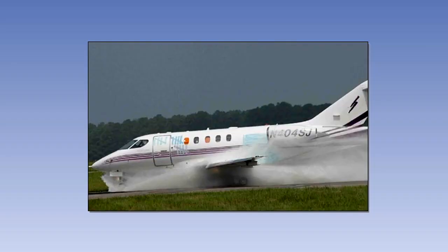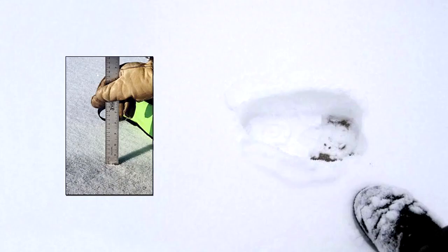There are other effects which runway contaminants can have on aeroplane performance, which include the possibility of a power unit failure due to water ingestion, directional control problems, and possible structural damage. It is therefore vital that the pilot be aware of the type of runway contamination, its depth, its extent, its effect on the braking, and of course its overall effect on the operation concerned.